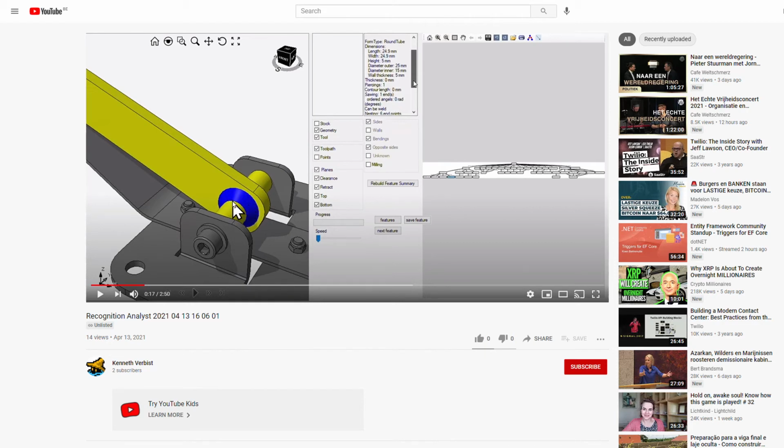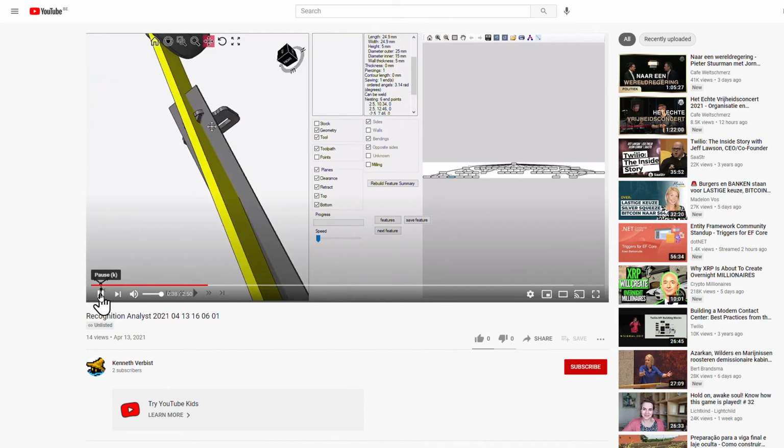Based on those characteristics, for example sheet metal with sheet metal, sheet metal with a tube, or sheet metal with milling or turning, we can use those combinations in the welding estimation, and we also know the full length of this welding. That's really valuable information for the welding estimation.